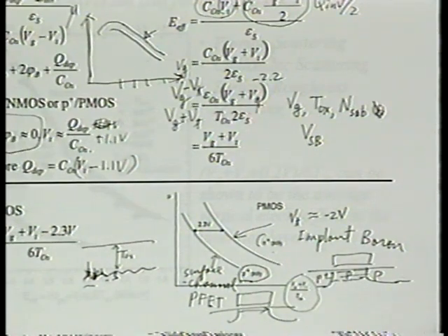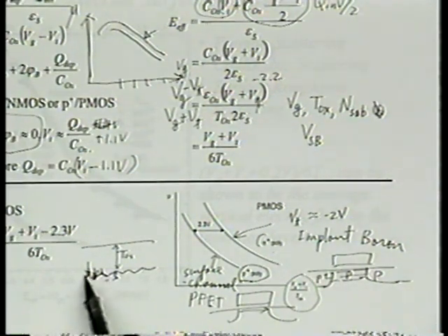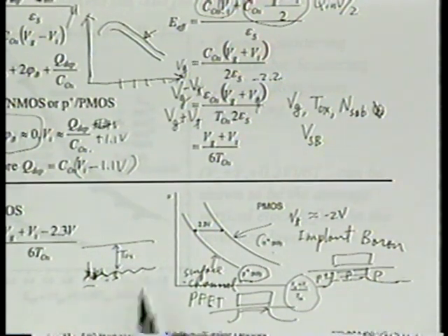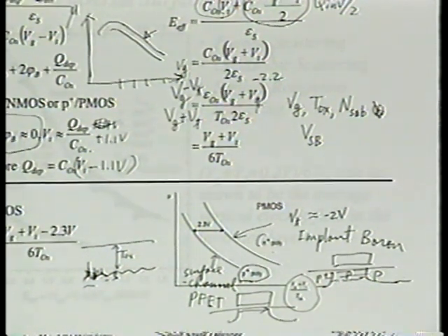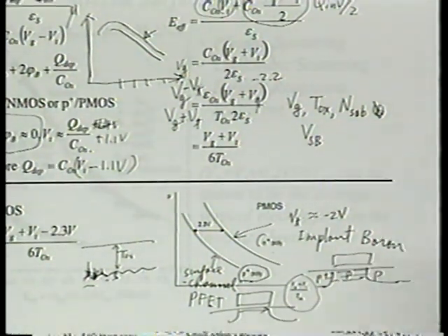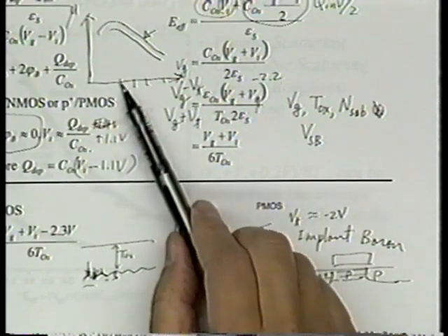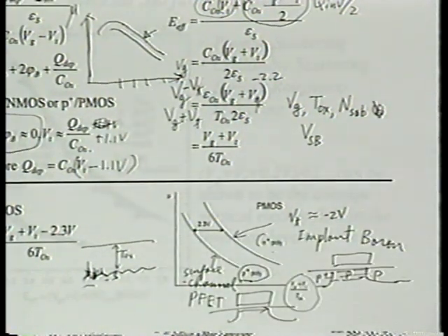And secondly, it's because of Coulombic scattering. You see, this basically went back to Coulombic scattering. It's a variation in the potential, so it's a Coulombic scattering. And Coulombic scattering is a fairly long-range interaction. So a few angstrom change in the location of the charge is not going to change that too much. All right. So whether it's a surface or not is not important to this. Okay. Any other questions about the mobility theory?